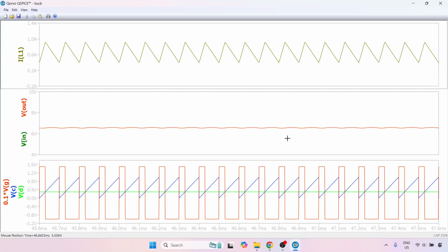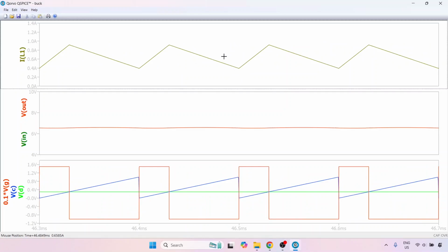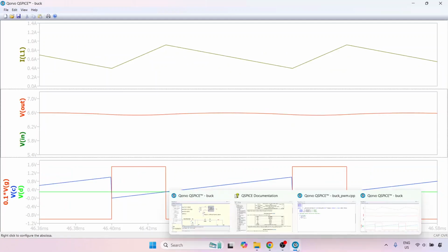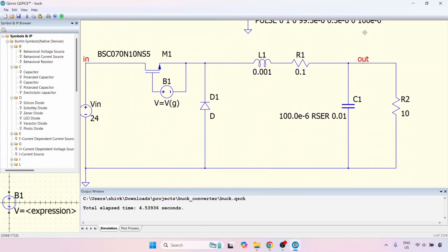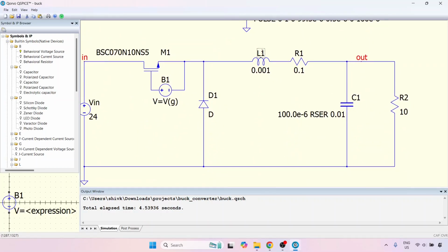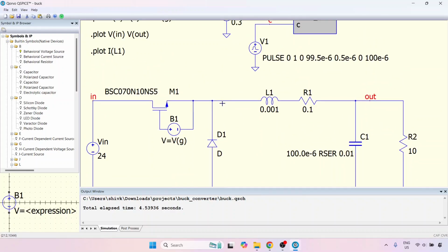That is, in this case, we are generating a high frequency gating signal. And this means that we are generating a current with a high frequency ripple. And this high frequency ripple is now being removed by the action of this filter. That is, we have at the output this inductor capacitor filter which acts as a low pass filter and removes this switched output voltage.